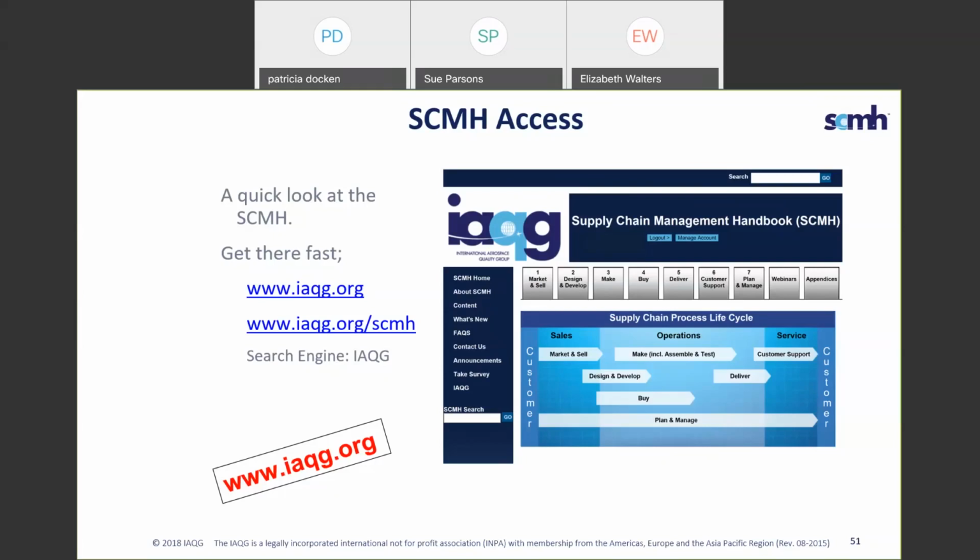Yeah, there's nothing that prevents anyone from establishing a control plan, but as we've mentioned, you want to use all the available inputs that you can to make a good control plan. If you just wing it, you may end up with many more elements that maybe you don't even need on a control plan. If you use the outputs from the DFMEA, the process flow diagram and the PFMEA to help you decide what goes on the control plan, you're going to end up with the important characteristics that you really do want to manage the variation on.